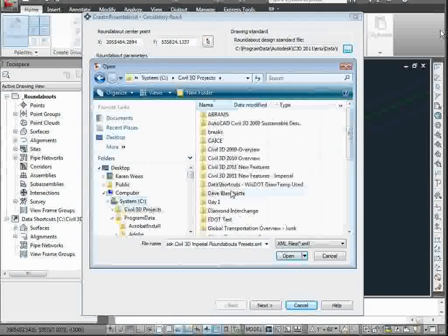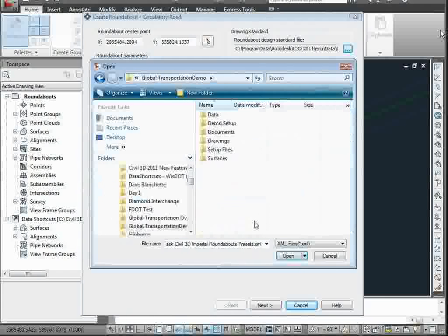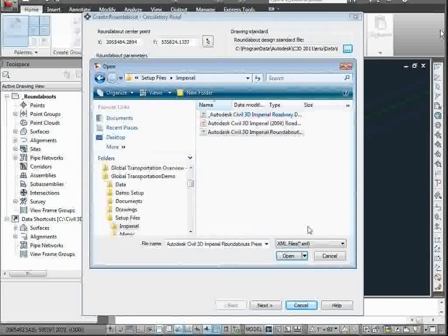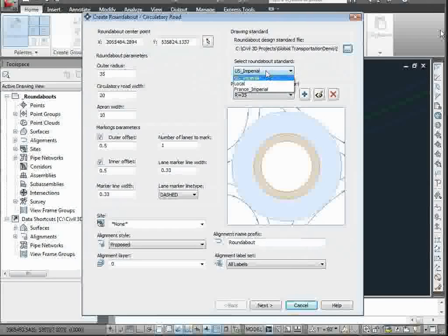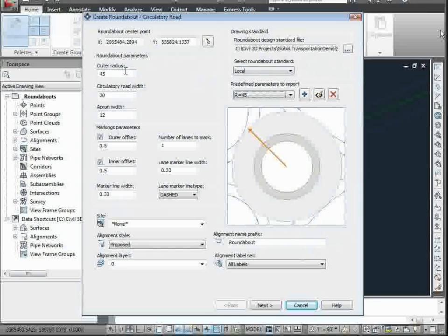So if in your community you want to see, will a roundabout work? Well, do one of those roundabouts by hand. All that geometry, all the tapers, it's a serious deal. So here you can use your own local standards for roundabouts or delivered standards. When you look at the roundabout, you can see, does that make sense for the deflection angles at this intersection? If it doesn't, let's do something else.